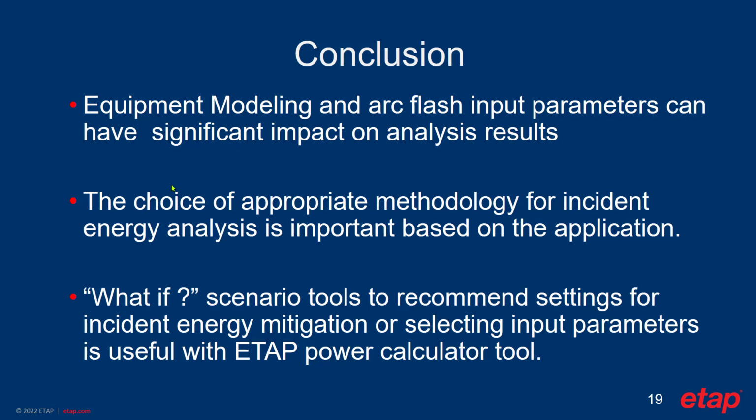And on top of that, for selecting the gap between the conductors on DC equipment where equipment access or measurements are not possible, the Stokes and Oppenlander method was used to estimate the gap between the conductors for this particular location where the maximum power method cannot be used.